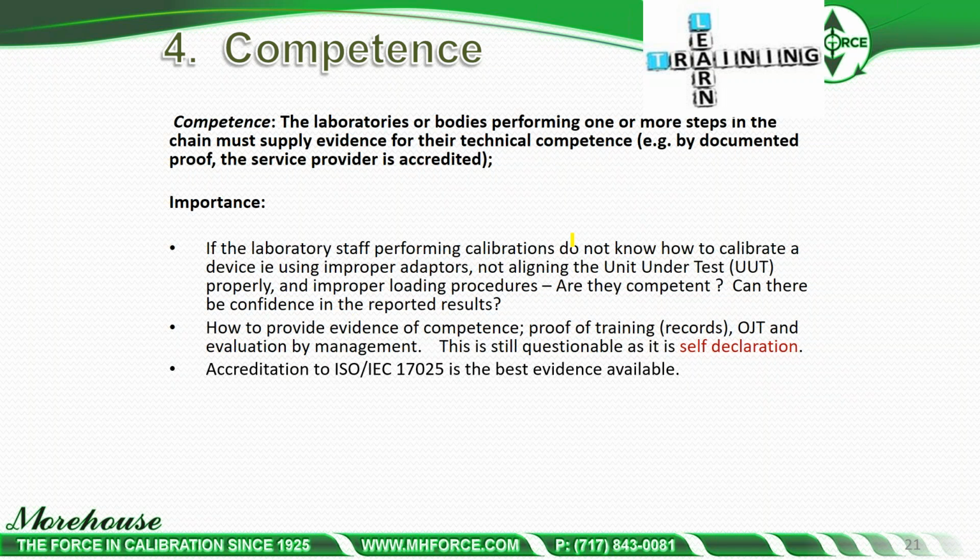R&Rs to make sure there's not a statistical difference between your technicians is good. Other things, just blind tests where you send an instrument through, have several people calibrate it, and make sure all the results are in. There's lots of good ways. Checking the records, checking if they're following the procedures.